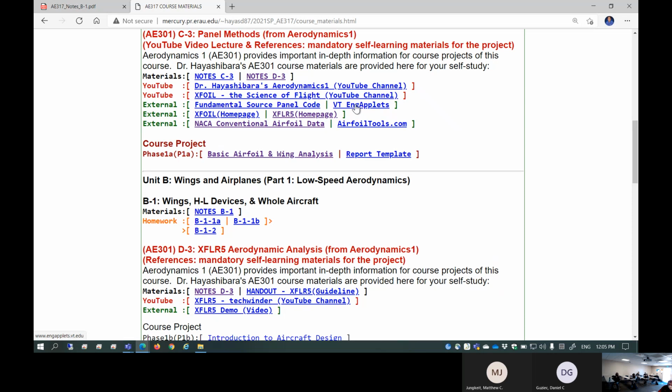If you want to use cross sections 1, 2 and 3, you need three databases to represent cross sections 1, 2 and 3 of a wing. Then you can use those databases to shape any wing, pitch up and pitch down, and predict your performance. However, that performance Reynolds number range must be covered in the database of the 2D airfoil.